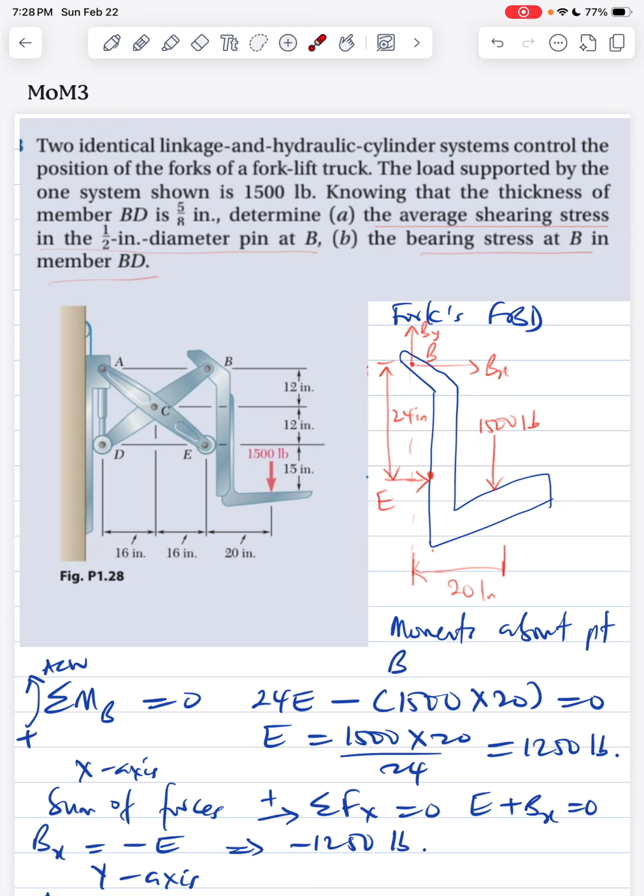Of course, the part that tends to dominate will depend on what the controller is trying to do, basically. But by principles of moment, bringing it downwards will force it to rotate clockwise, and this will move anti-clockwise, right? So if you look at E, E is the force here. With respect to where you're taking moments, you're trying to find the effect of the force at this point, the turning effect. So that's 24 times E. Now, this is acting downwards, right? Trying to turn this way.